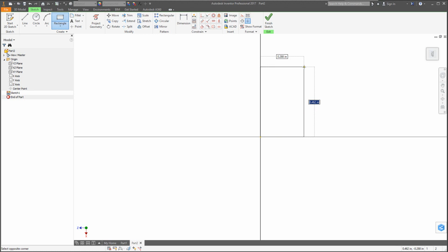If you have your number lock on your little keypad to the right, you could go ahead and type in a value. Just be aware the number lock key has to be activated in order to get that to work. Or else you could use the numbers on top of your keyboard. But here, this needs to be 5 inches in height. So you don't have to type in 5.00, just type in 5, but don't hit enter. Instead, to add the next dimension, click on that dimension up top. And it disappears for a second, but that's okay because it's just getting out of the screen a bit. We could fit that. And this needs to be 3 inches, and this is the width. So just type 3 and hit enter.